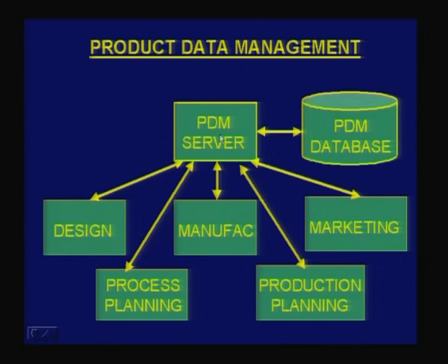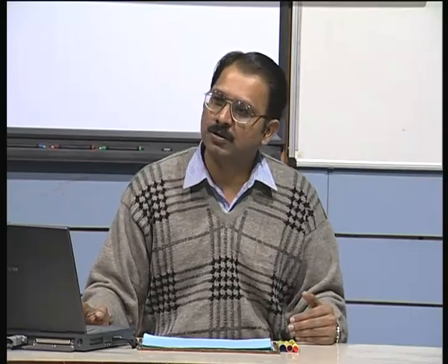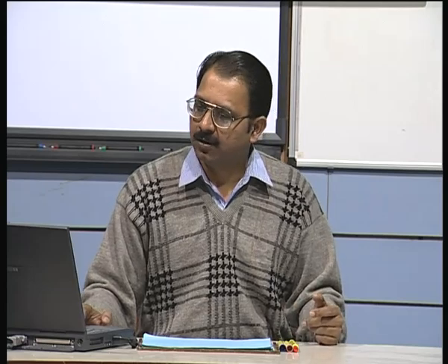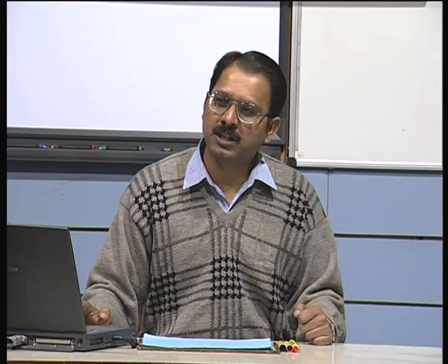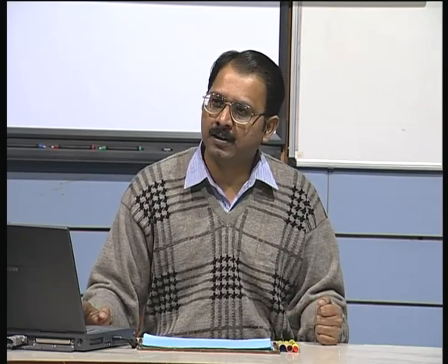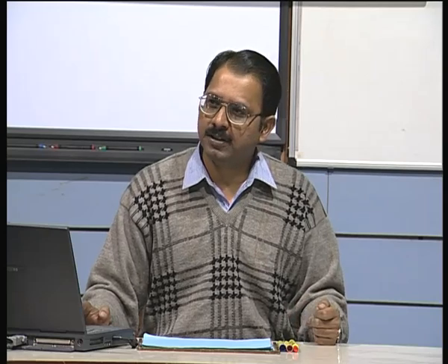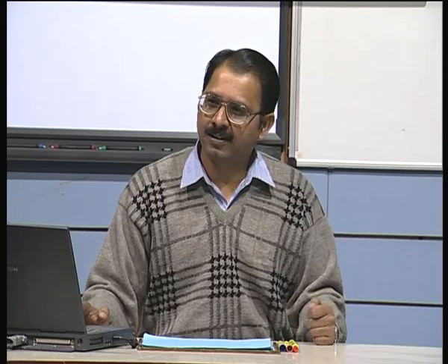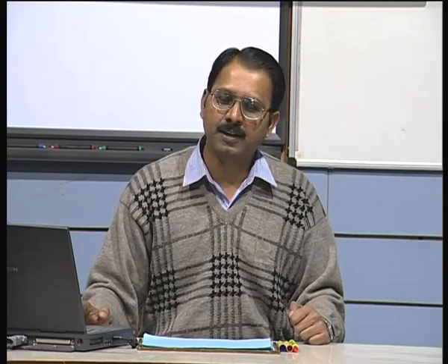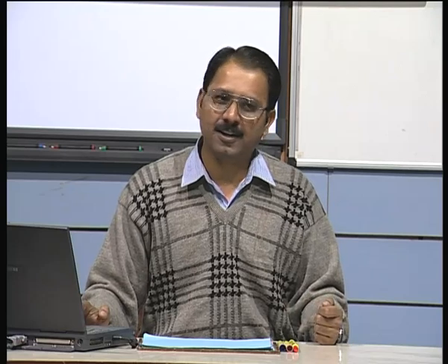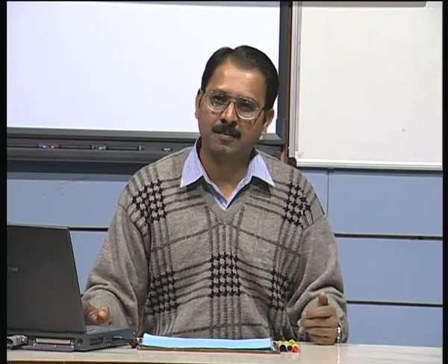Since product information is critical to many people, if everybody is modifying it, they can post it at a central place. So, this will have various versions. Suppose the design has undergone, let us say, 10 changes, from version 1, 2, 3, all the designs are stored. If somebody wants to refer to why this has happened and how it has happened, one can always go back. PDM can store information in various ways. It can be a text file, an image, an IGS file, a STEP file, or CL data, that is cutter location data which has been generated as a part of a program.